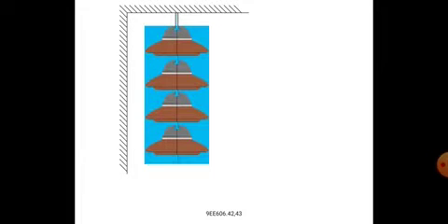The metal work cap is connected to the link of each disc, with a capacitance relative to the metal work of the next disc. So each disc has one capacitor, horizontal and vertical. The capacitance of the metal work of each disc relative to the metal work of the next disc is known as mutual capacitance, and the capacitance of the metal work relative to earth is known as ground capacitance.